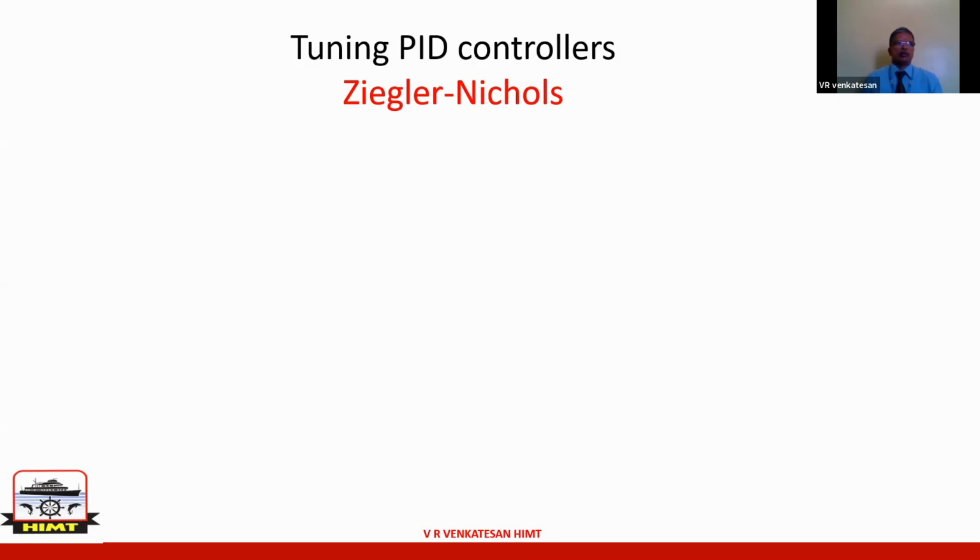Depending on the type of controller, your controller will say either KP, like electronic controllers often have an option for both, but a pneumatic controller will have only one. And most pneumatic controllers you would have seen have proportional band. And the relation between band and gain is that it is the inverse. If proportional gain is more, it is the same as band is less. So there are two ways, meaning same thing, but two different ways of adjusting proportional. That is KP and PB.